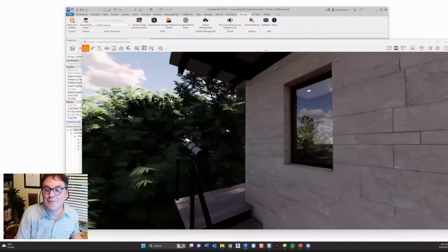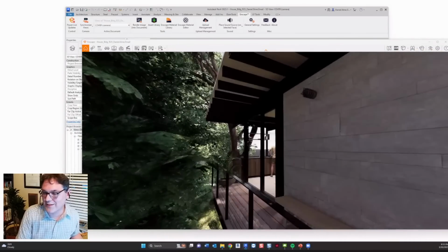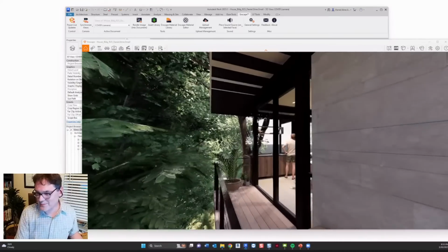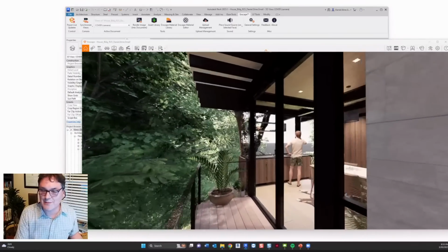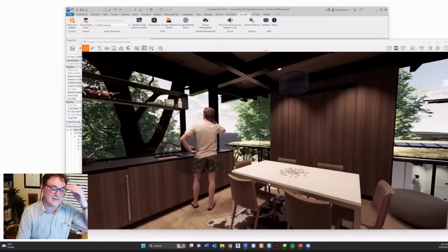There's more sophisticated proactive ways where you're not always working like you're in AutoCAD. Worksets were originally designed to control resources, right? So if you turn off a workset while you're opening the Revit model, it's like it's never there.